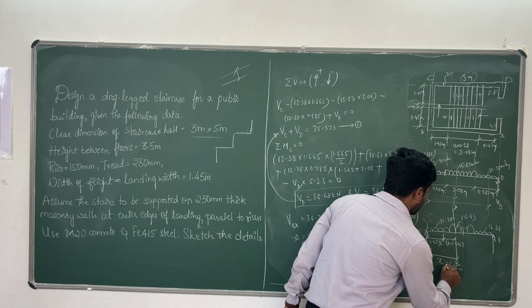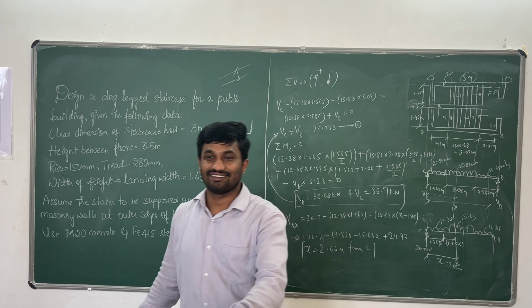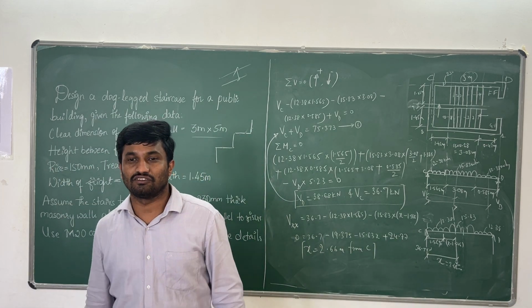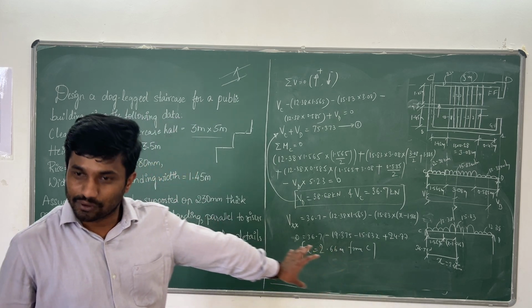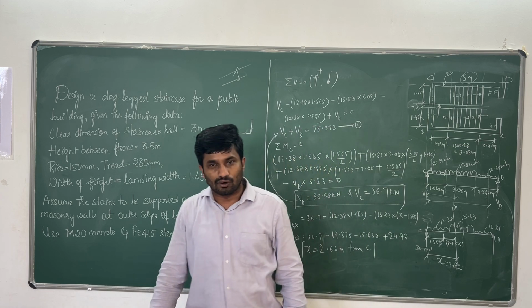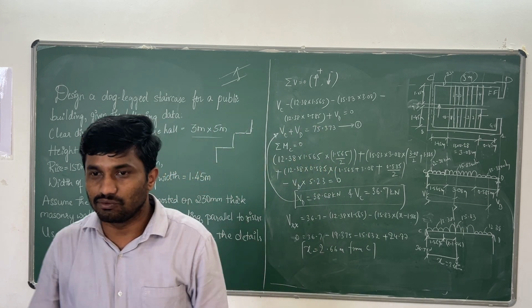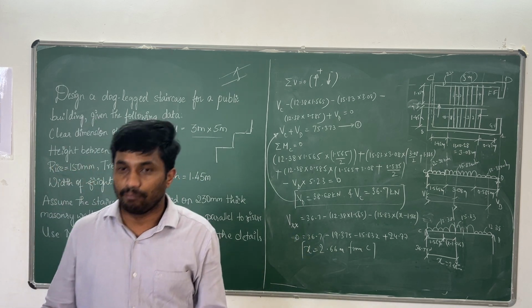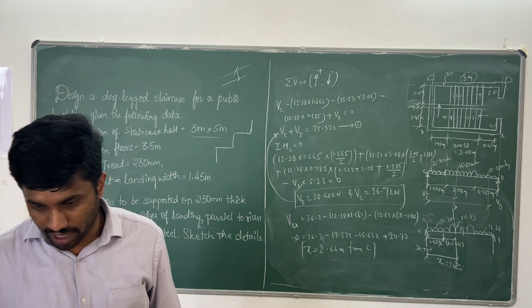Now for this point you have to compute the moment. That is the maximum bending moment we are considering for design purpose. Clear? How to compute the x value where the shear force is 0? At that point we are getting maximum bending moment. That is the concept behind this. So next compute Mu.